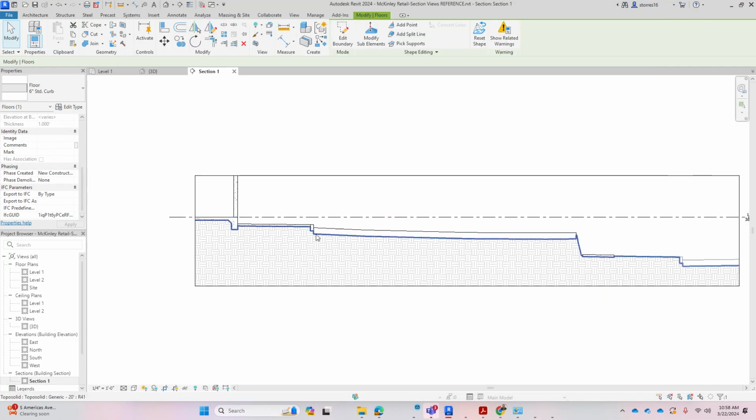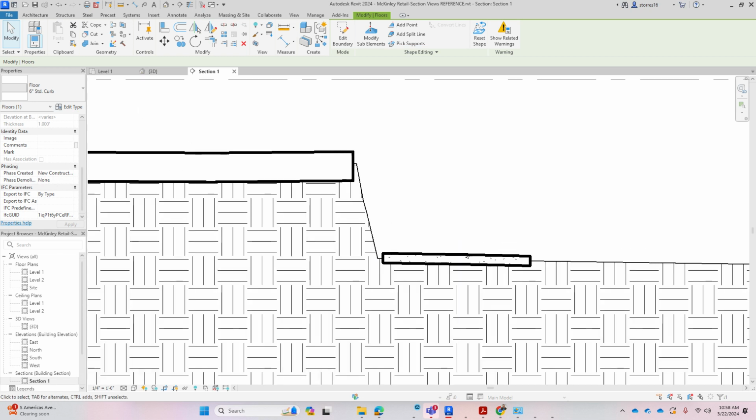So on your section view, once you get to draw that one, I guess I'll draw back the retaining rock wall again, where we have the retaining rock wall here roughly, and then we have this guy here, and then drawn like that. So then here we also need to show our property line. So the property line will be on the face. So you just draw, I guess let me put in a bolder line right in here. The phantom line would be like this, and then obviously along the face of the wall. And then remember how we always have sidewalks usually within the right of way, and then that's where you're going to start labeling that, and you would put text.